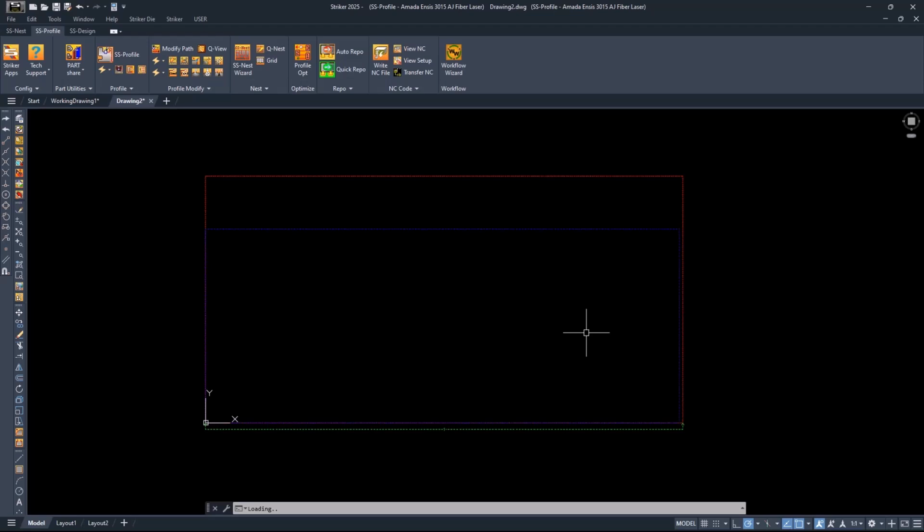So it's just a matter of, I have to put a tool path on here. I have to make sure that I'm using the correct cut conditions based on the material type and gauge that I'm running, and what type of lead in and lead out, where it's going to be, and tool path optimization, and there you go.